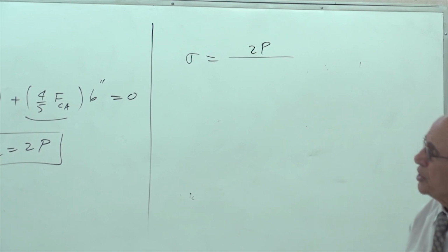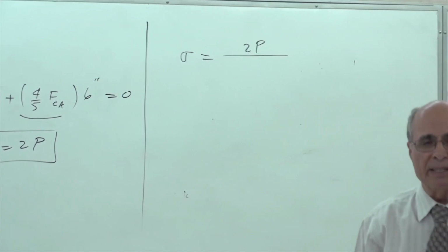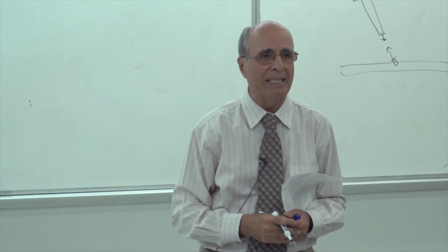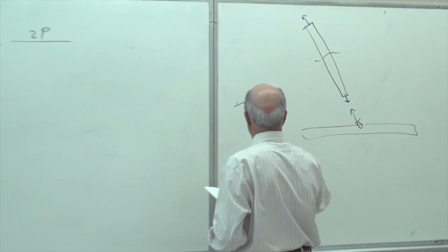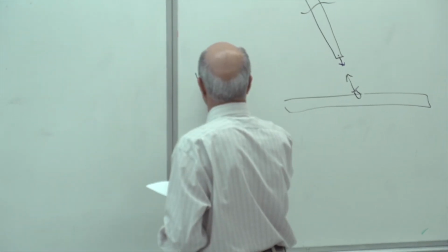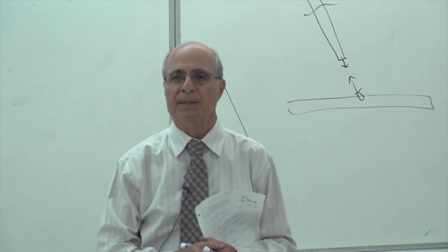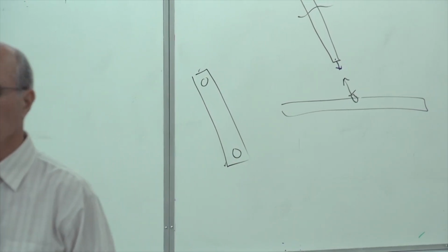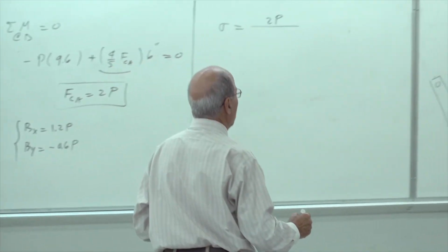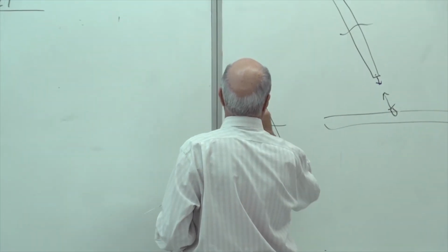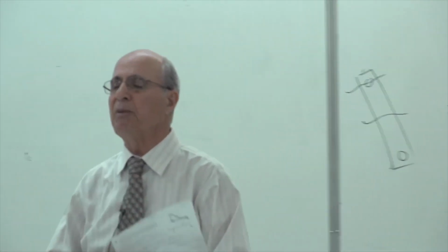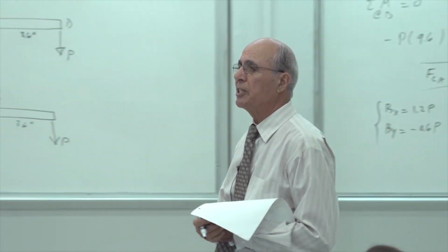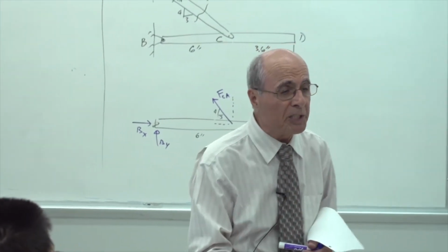The area is 1.5 inch by 4 inch. Really? Is there a hole there? Is it a pin there at the beginning, at the end of that rod? That's what I was talking about at the beginning, guys. Is this like that, or is it being reinforced? It doesn't say anything. The picture doesn't show anything. So I have to subtract it. It is under tension, but this cross-section is much weaker than this cross-section. That's what we had before. So I have to subtract the hole, because it is not in the compression mode.